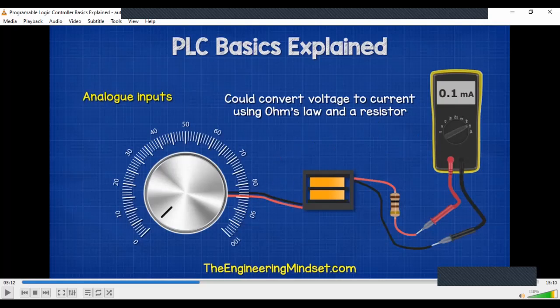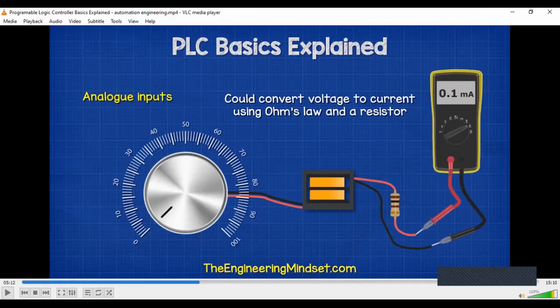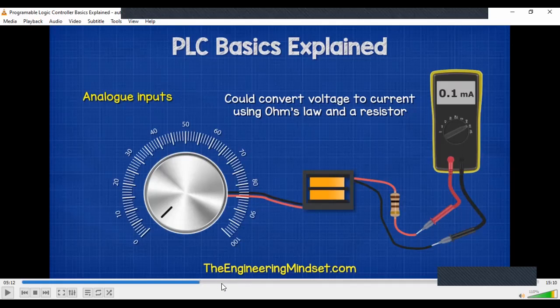If it is a digital one, nothing is required, right? It's just either on or off. So either this or that, two things. But here you have a specific value for analog things, so you have to have some sort of conversion, and there could even be sensitivity issues. So for the PLC to understand, it either scales it down or scales it up. Okay, magnifies. So if it is too small for the PLC to understand, it will scale it and then understand what is actually the status of the input. That's what we mean by sensitivity. How sensitive it is depends on the different PLCs.